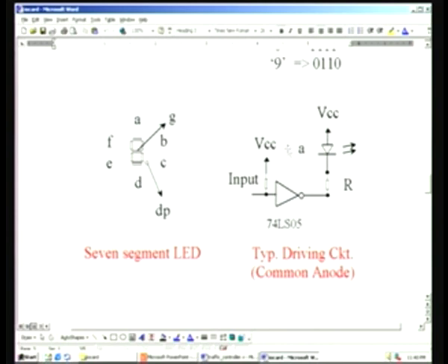That is why all the 7 segments are combined together as far as the common anode is concerned, and when it is 1 here, it will be 0 here, and this is the current limiting resistor, and naturally the LED will conduct. A typical resistance is around 200 ohms, which you can easily find. A conducting LED will take about 1.5 volt, and this will be 0.3 volt with reference to ground. That means 1.8 volt drop is accounted from the plus 5 volt supply.